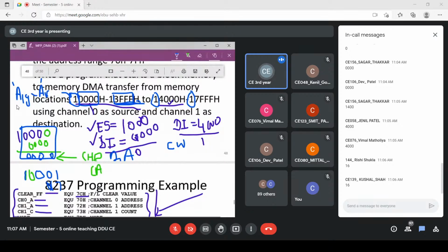I told you earlier also, we have already discussed this. So you are going to adjust A9 to A16 in such a way that whenever the combination of A9 to A16 becomes 0001, the chip will get selected. That is hardwired, right? So we will not be concerned about these earlier lines. What we have assumed, it is hardwired. Okay.